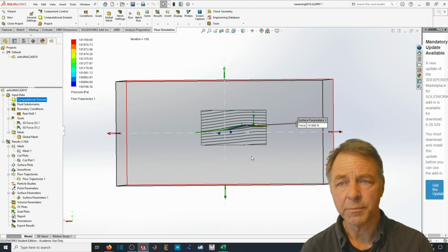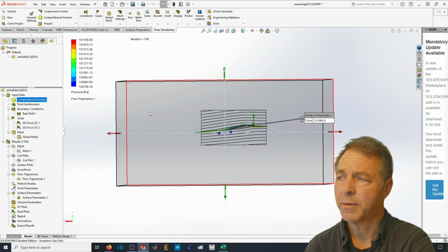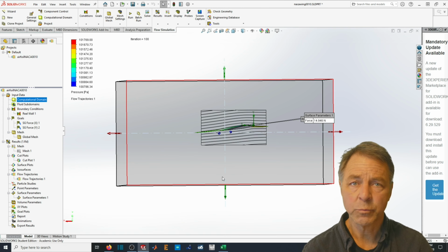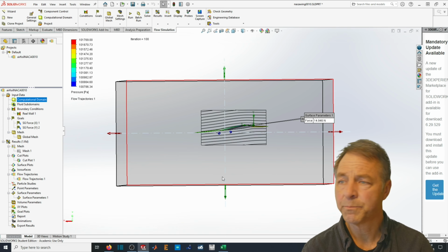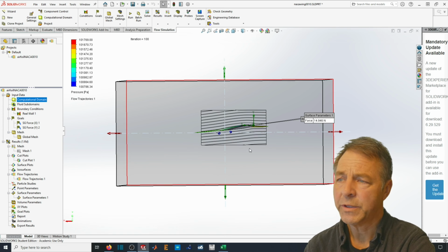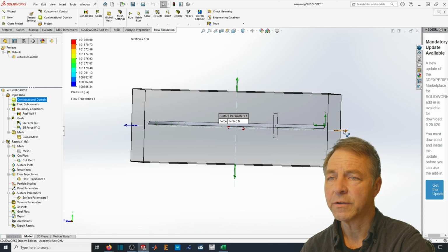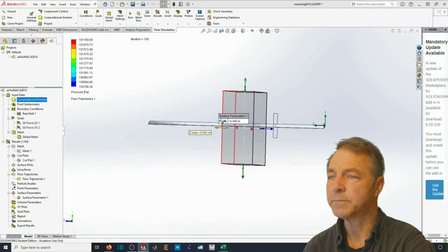So there's the problem. If we tried to rerun this simulation with a domain this size, the time it will take to solve will be hugely different because we've just created a whole lot more grid points, and that's going to cause a real problem. So one way we could improve things is, do we really have to have the calculation domain the full length of the airfoil?